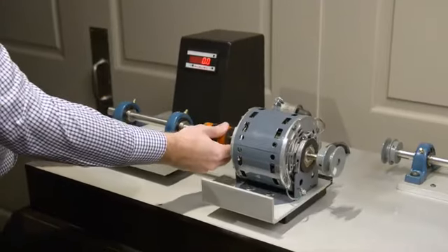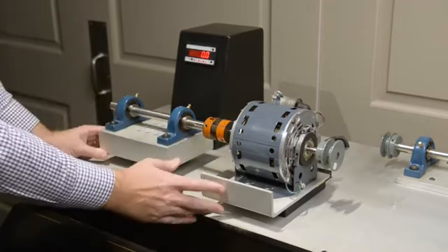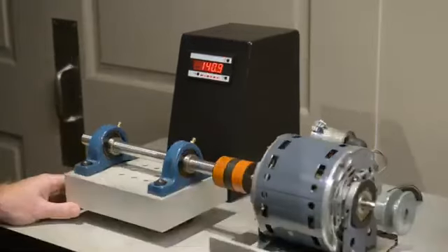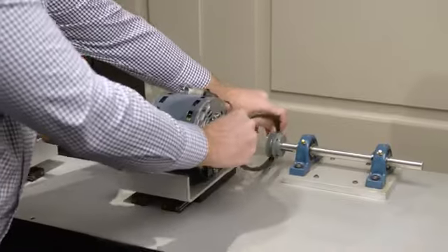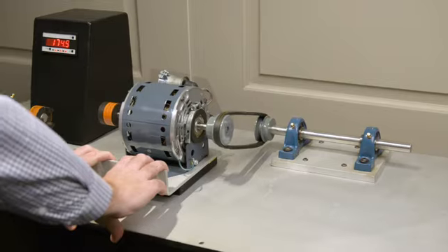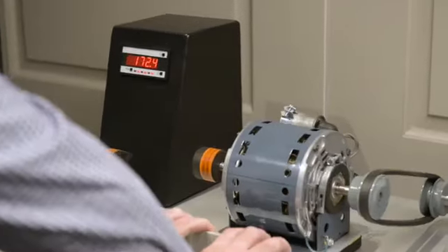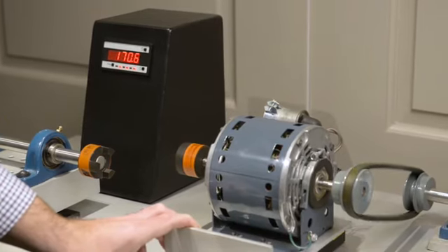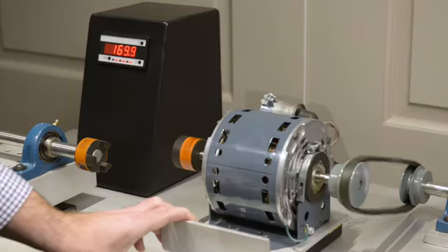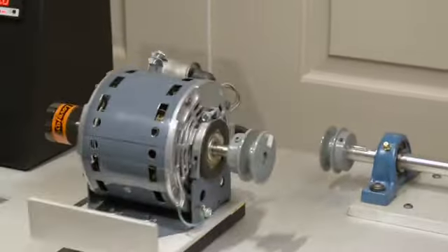When we connect to a shaft and bearings via a direct coupling, the power consumption jumps to approximately 140 watts, an increase of nearly 15%. If we connect the motor to the shaft and bearings in the conventional method with a common V-belt, the power consumption jumps again, this time to almost 175 watts, varying as the belt tension changes. The additional energy is related to the friction between the belt and sheave, and the energy necessary to flex the belt as it goes around the pulleys.